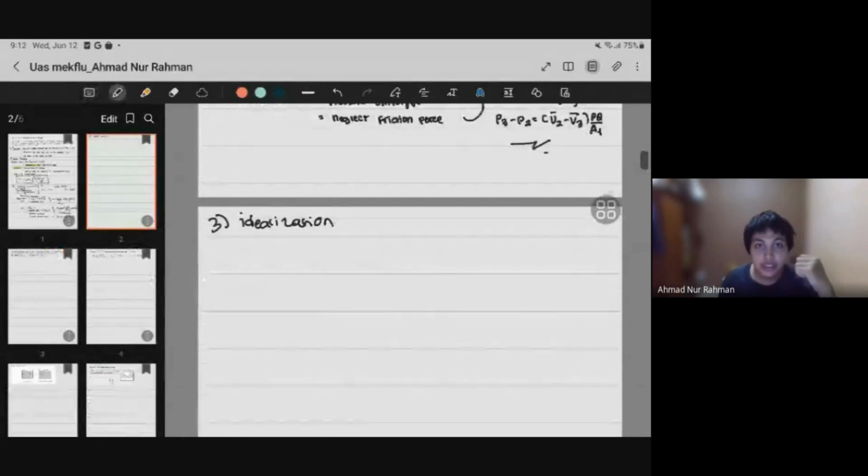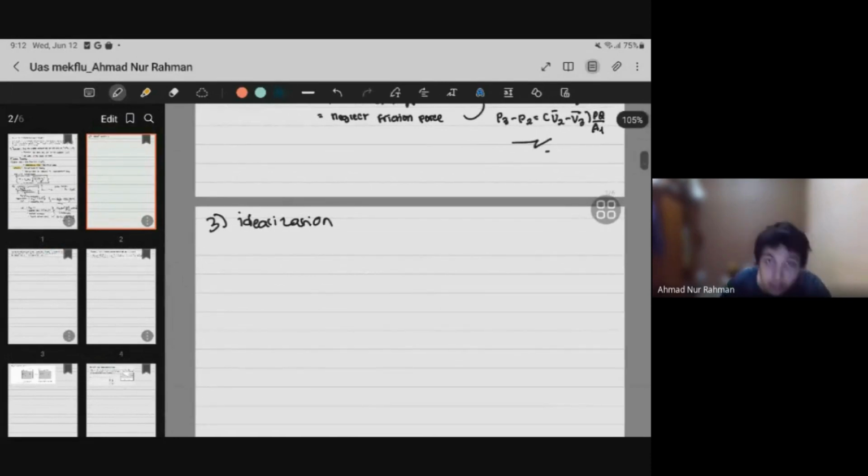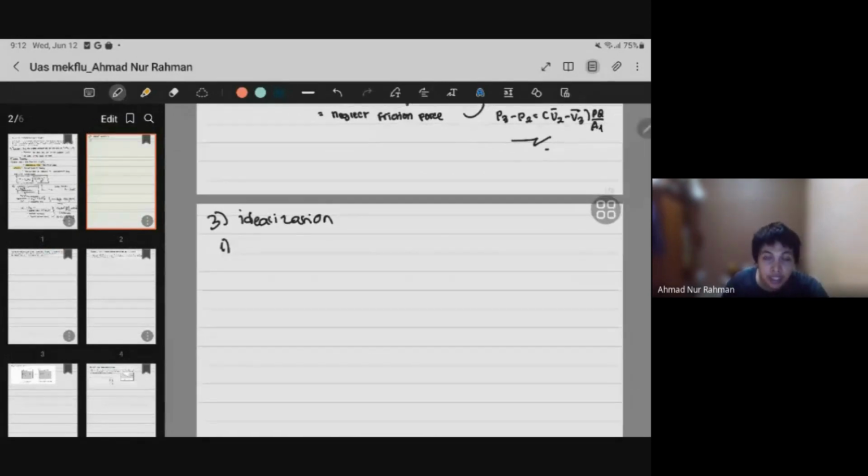Next we get to the analysis process. So we are going to solve the first problem. Because we need to search for pressure, the mass flow rate m dot equals C_o A_t times the square root of 2 rho (P1 minus P2).